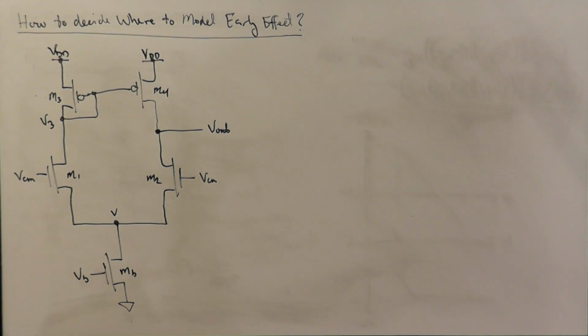And then the second phase of the calculation is calculating the incremental output resistance of the circuit. In that case, the output voltage being held fixed by a voltage source is not actually an inherent part of the deal. Okay, now we do use that voltage source conveniently to actually do the calculation, but what we are probing in that particular case is the incremental output conductance of the circuit. That's actually different than the incremental output resistance of the circuit, where formally the excitation signal would be a current source excitation, and the response of the circuit would be the output voltage change.